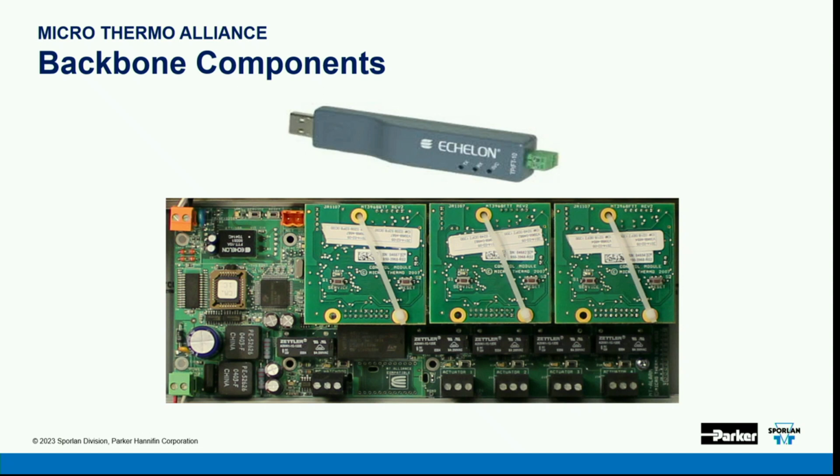Again, I would start and stop this channel. Do not continue the network from the alarm node. This is such a critical node and so much information is going in and out of this node. This should be a drop unto itself. You know what I'm saying? I always pull this plug out of here because I don't want somebody to continue the network from that plug, so I pull it out, all right?